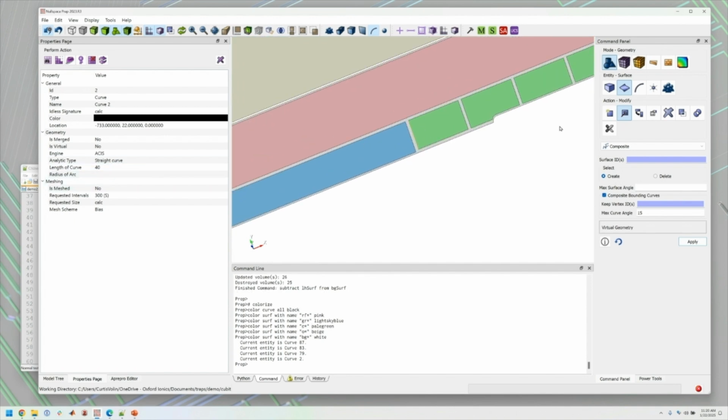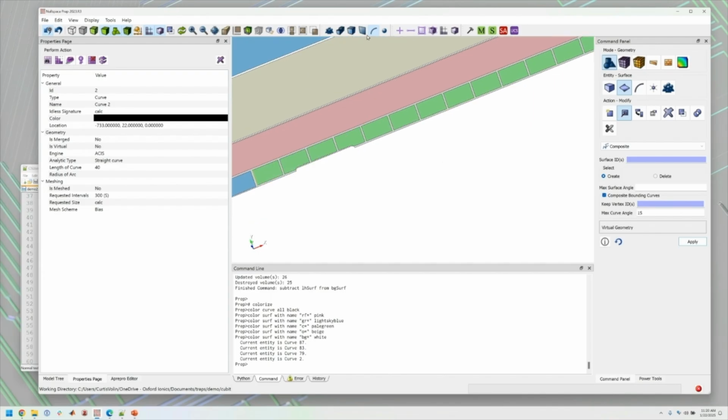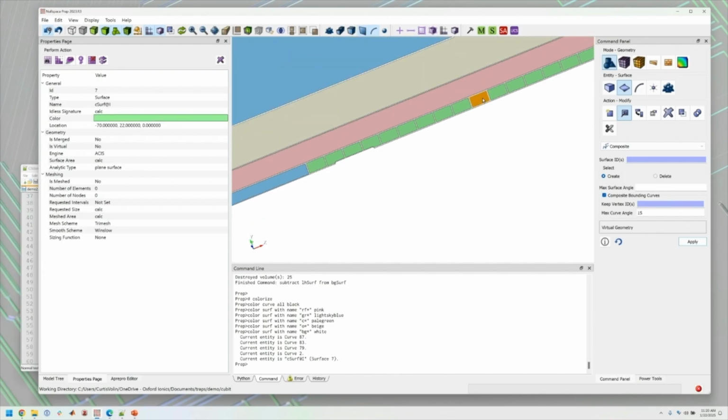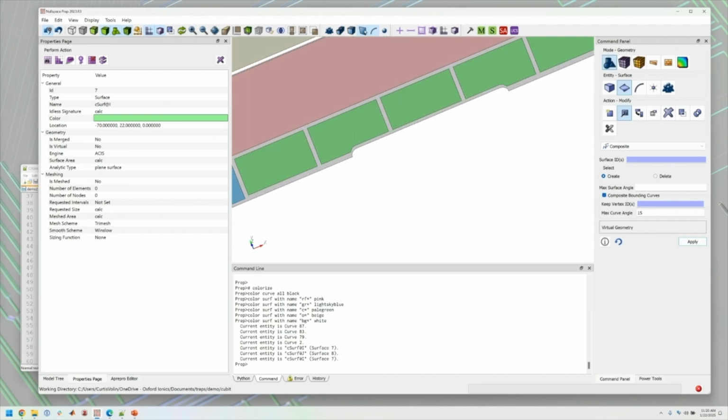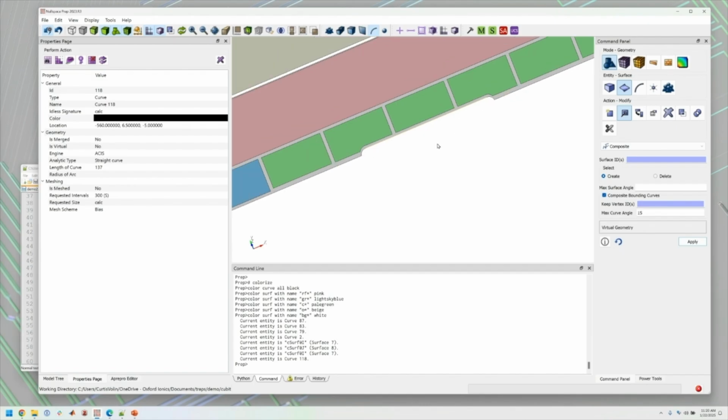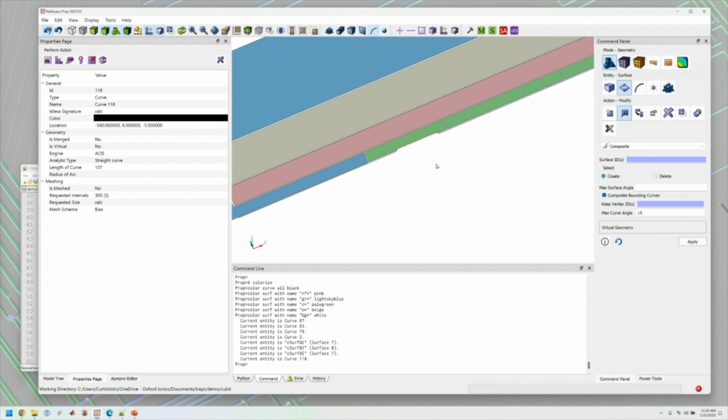This electrode is 40 microns wide. If I go look at one of these electrodes, you can see the pitch is 70 microns. So this guy's at x equals 0. This one's at 70. And then we have this load slot down here, which is 13 microns wide, and you can see from it being about 2 electrode pitches that that is right about 150 microns long.